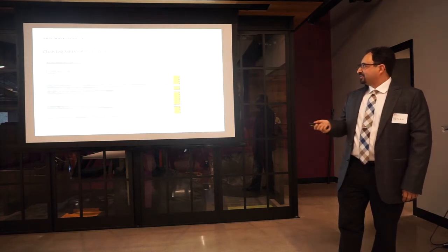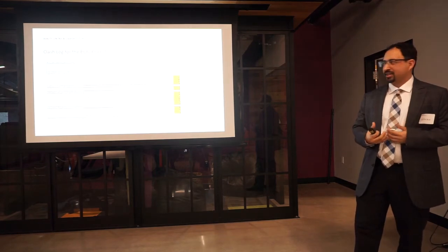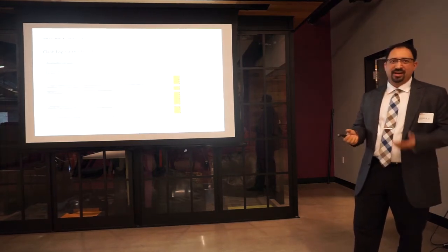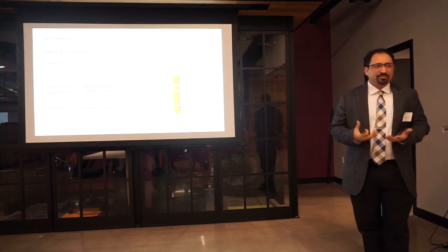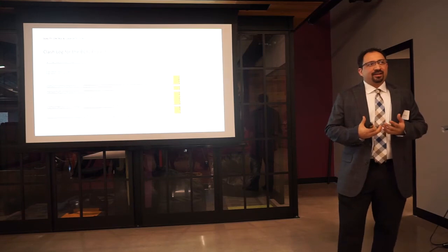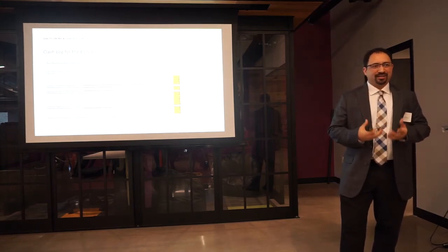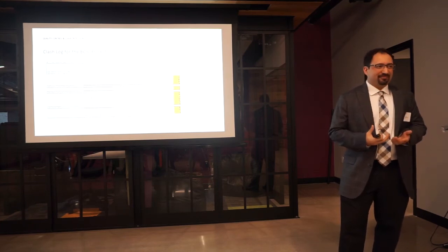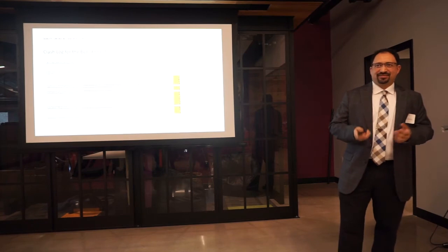I thought this would be interesting to see. Here is our own clash log from our project. So at one point we had about 2,000 clashes happening, and with the nature of the project, as you're adding more information to the project, the rate that the clashes were growing versus the rate that the resolutions were found was not exactly the best for the first few months.